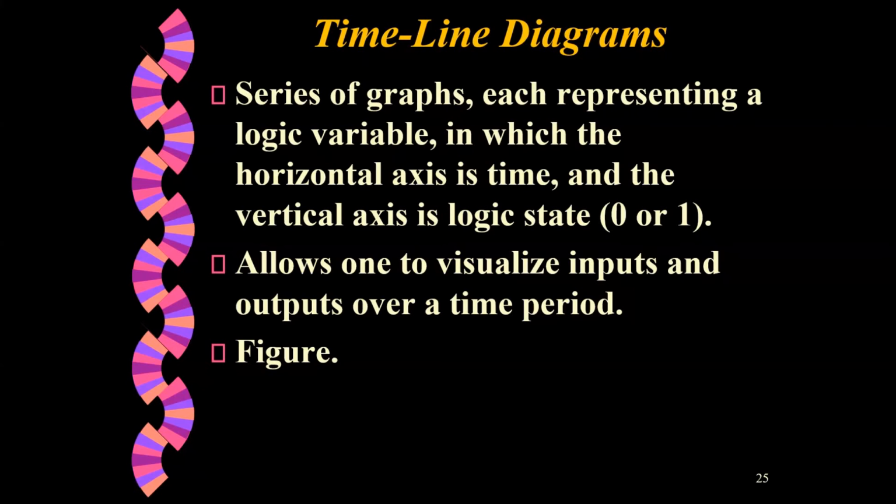And if they are too cumbersome or unwieldy, compress it using theorems and so on. Then you have a set of equations. How do you know they are correct? Best is, before you go to the PLC, draw a timeline diagram to see whether the timeline diagram exactly shows you how the process is going to behave.